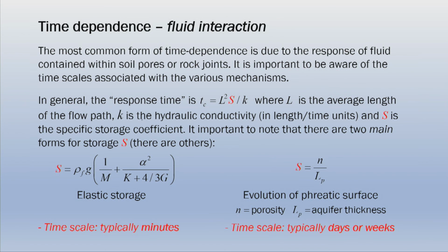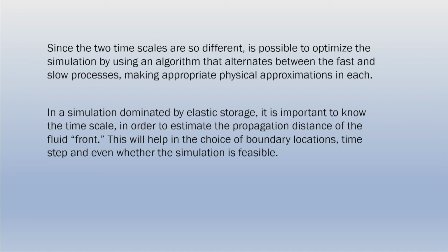One big thing with time dependence is fluid interaction. So this is a common form. And what I think people should realize is that there are several time responses. In general, the response time is related to this storage coefficient, S. And there are a couple of forms of this. This would represent elastic storage, and this would represent the migration of the phreatic surface. And typically, the time scales are totally different. These are in minutes. These can be days or weeks. So you should take this into account when you're making the model.